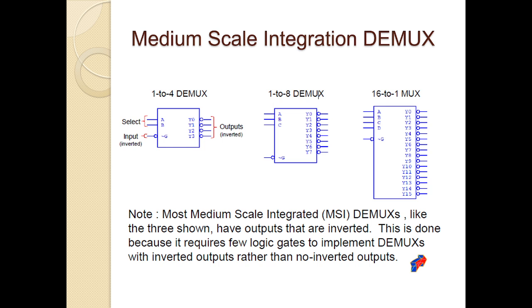These are the logical block diagrams of the 1:4 demux, 1:8 demux and 1:16 demux. In the 1:4 demux, the input is 1, the outputs are y0, y1, y2, y3 and the selection lines are 2, because 2 power 2 gives 4 outputs; they are A and B. Likewise in 1:8, the input is 1, the outputs are y0 to y7, 2 power 3 gives 8 outputs, so 3 selection lines, considered as ABC or S0, S1, S2.